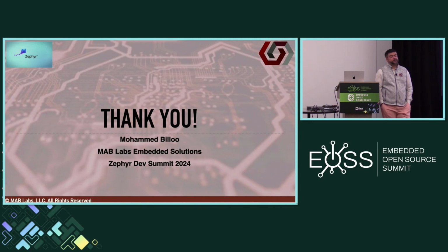Right. And then the idea is to implement the remoteproc the other way around. But as a stopgap right now, we're just going to boot Linux first and then the other way around. But the notion is that you have this fast RTOS booting, doing your pin muxing, and then 10 seconds, 20 seconds later, whatever, depends on your Linux, right? That comes up later then.